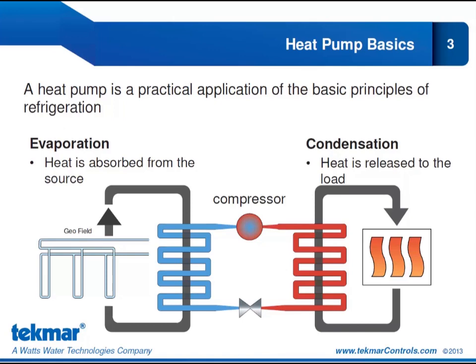Now, most people are familiar with the concept of a heat pump and that it is an application of the refrigeration cycle. And just like a refrigerator, heat pumps are designed to transfer heat from one location to another. So just like the image we have shown on the slide, we are absorbing heat from the geofield, and then the heat pump is able to release that heat to the load. The difference between a heat pump and a refrigerator is that a heat pump is reversible, so it's able to operate in heating and cooling mode, unlike a refrigerator.